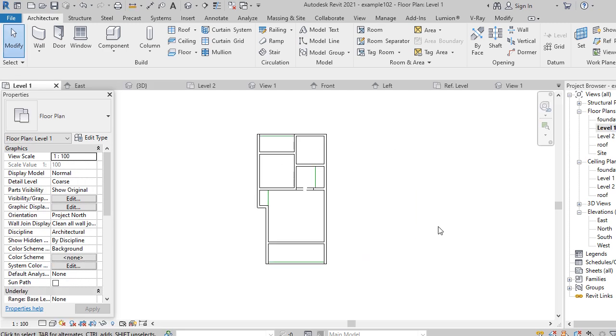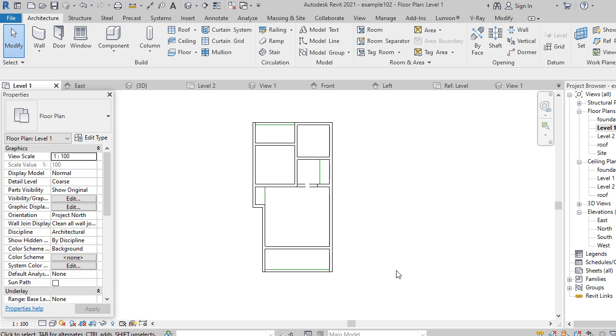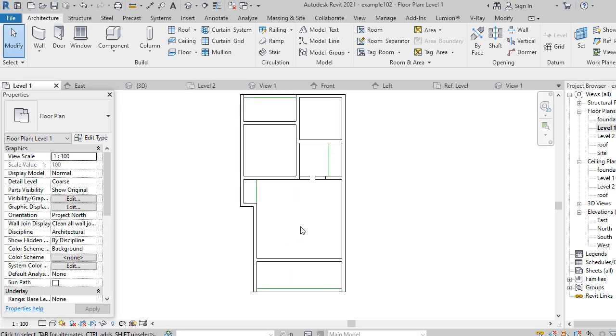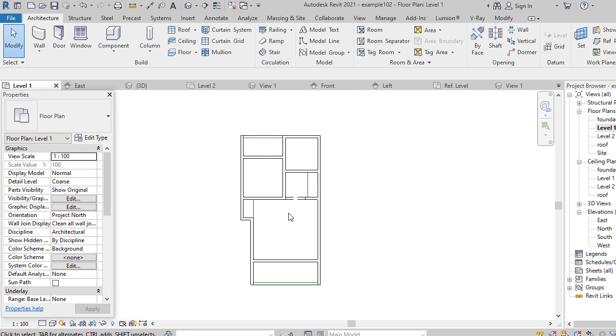Now when you're working on a project, alright, as long as the modeling process is concerned, you're going to have a lot of things. Alright, you also need a 2D representation of your drawing. Alright, so here now we have this. Next thing I want you to take note of is that you will have to add your doors and the rest of them and put dimensions for documentation purposes. And then we add dimensions, and then we can duplicate it and use the other copy, duplicated copy, for our modeling purposes.